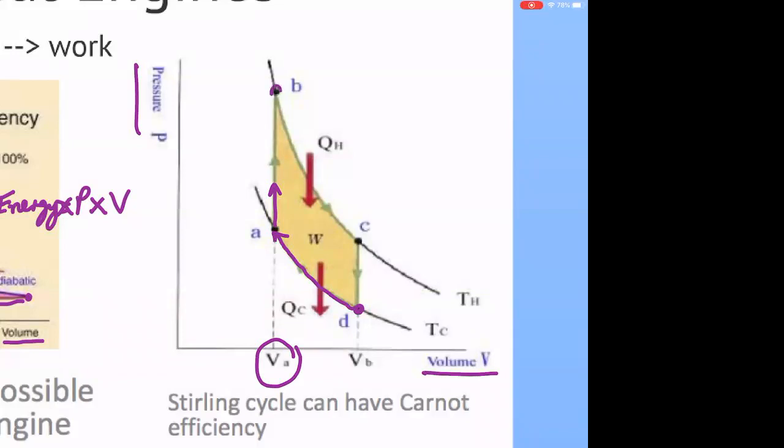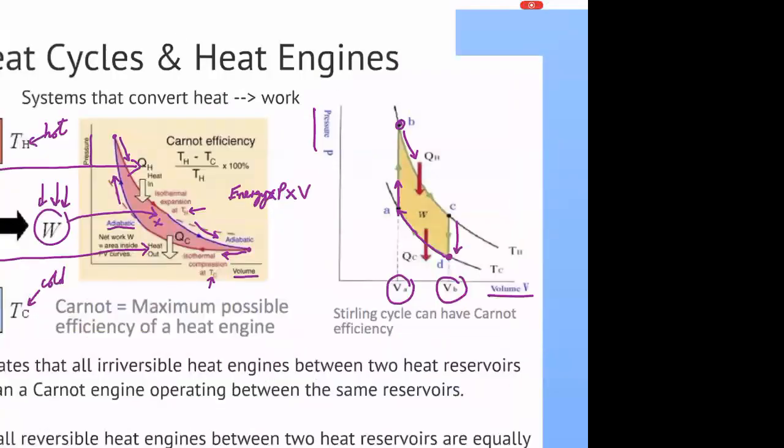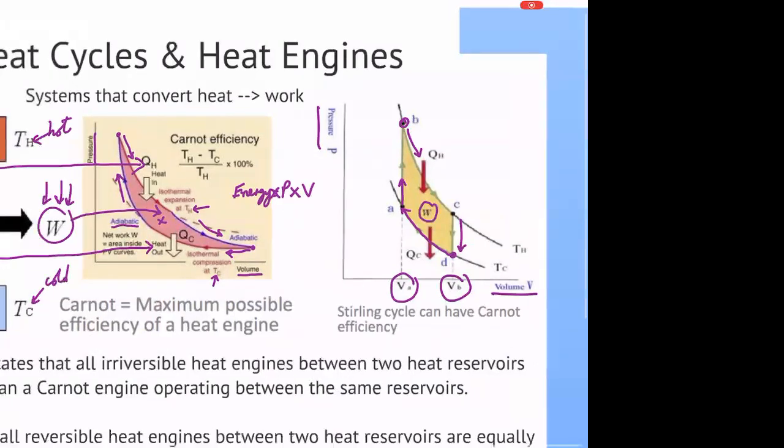And then from that point, you allow the fluid to expand. Again, heat is drawn from outside the system into the system. And then you have a constant volume decompression. So pressure is decreased while the volume is fixed. So slightly different situation, and you can actually show that the area under this curve, which is the work done, is always less than the work done in the case of the Carnot cycle.